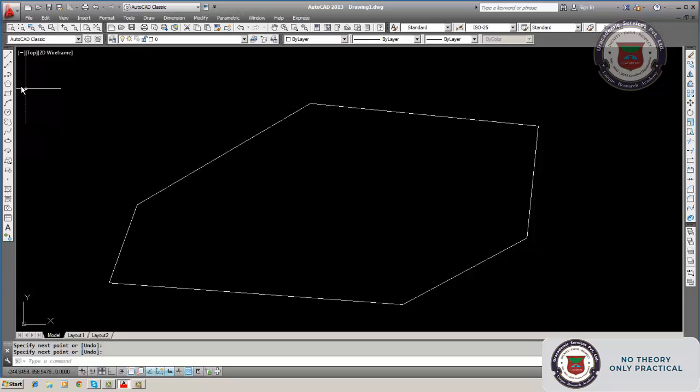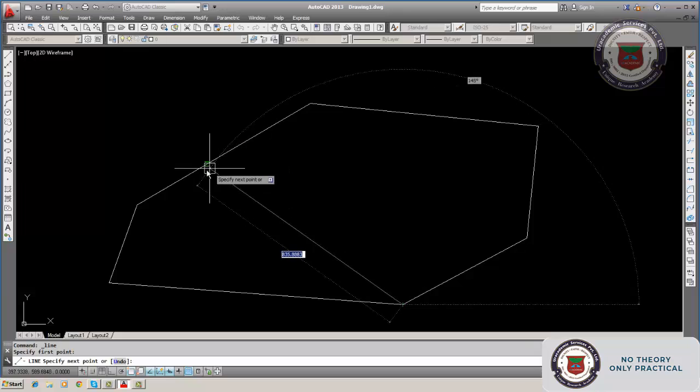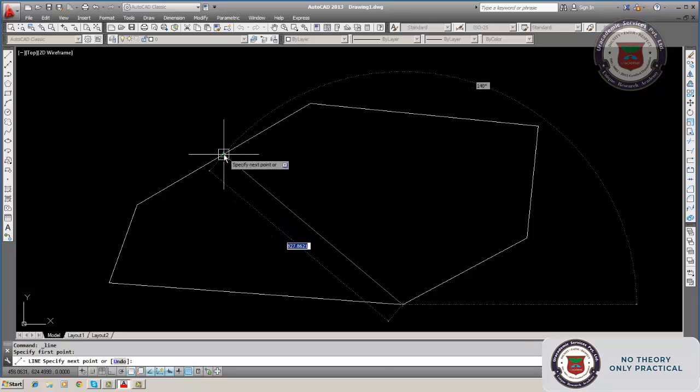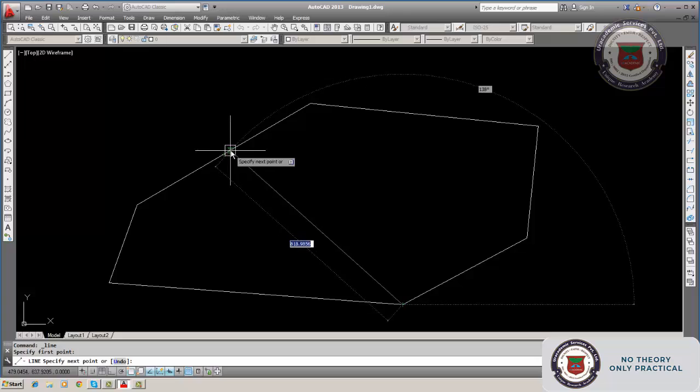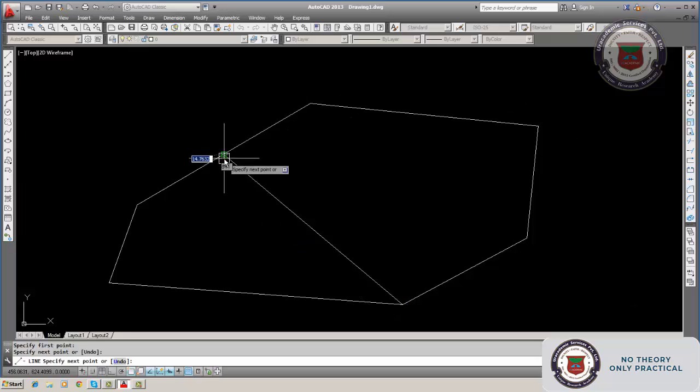So what we do is, as usual, click on line and focus on the end point and joining point of these two. End point of this line or this line, the same. And now we bring it here, and here it may be anywhere. So midpoint, a triangle is shown here. See, midpoint. It indicates midpoint. And this is not midpoint. It indicates a triangle, equilateral triangle, green color. That is the midpoint. You can click it here.